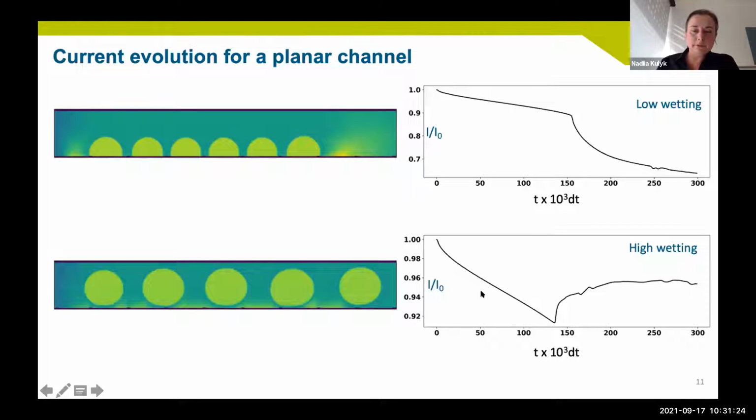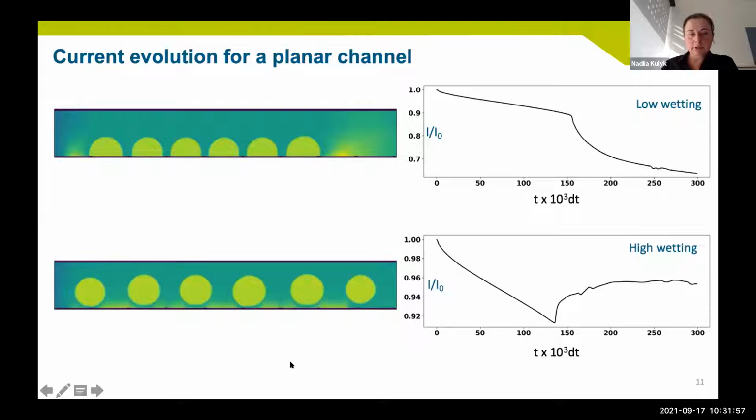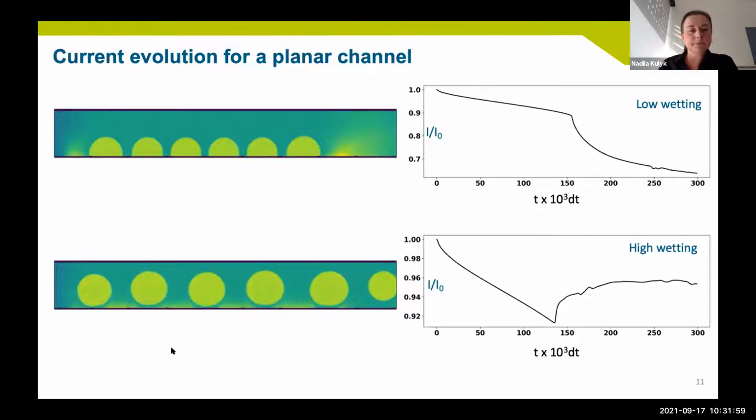For the lower one, it's a high wetting electrode. The bubbles form and the current goes up because the bubbles absorb the oversaturated reactant product. And you can also see the flow. They will be flying away from the reactor. You can also see that next to the bubble, the concentration of the product is lower than next to the electrode.